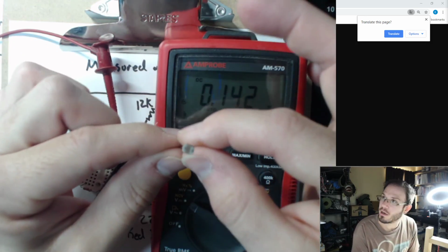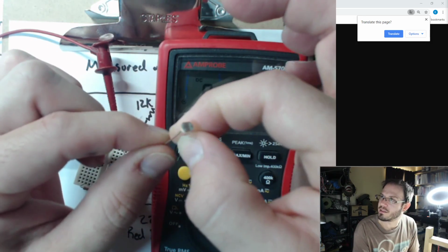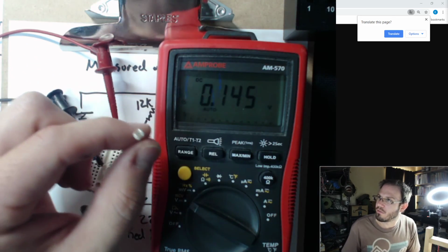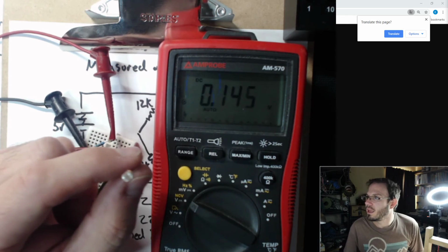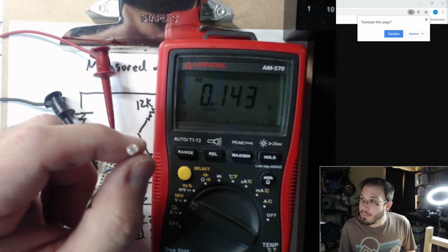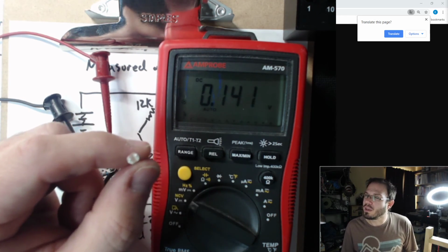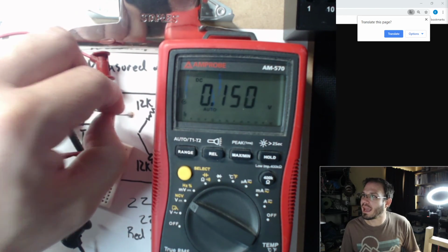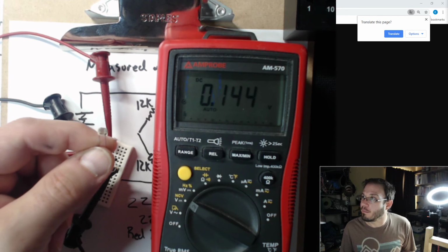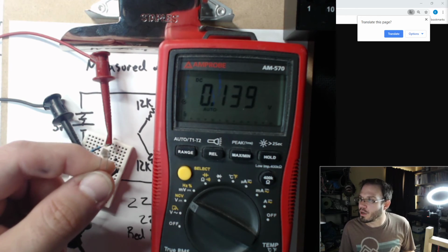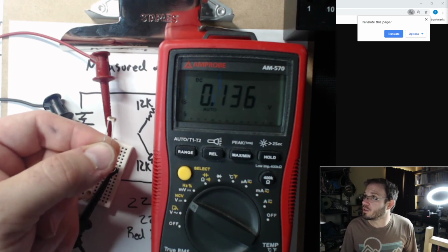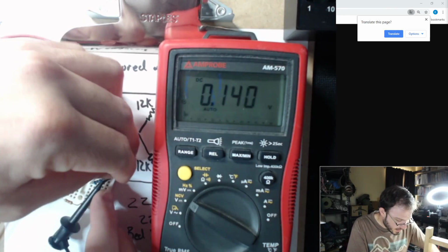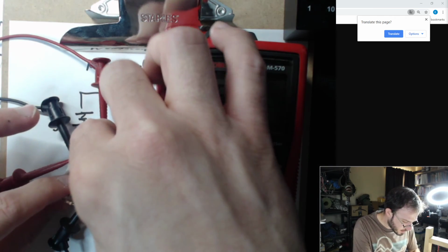So what I have here is a little light sensor. This is known as a cadmium sulfide cell, and these are great if you want to make a line following robot. You can use this to detect black versus white, because white reflects more light. You can use this as a motion sensor. Your motion sensor lights, they all do this, and they usually use something like this. And in place of this,